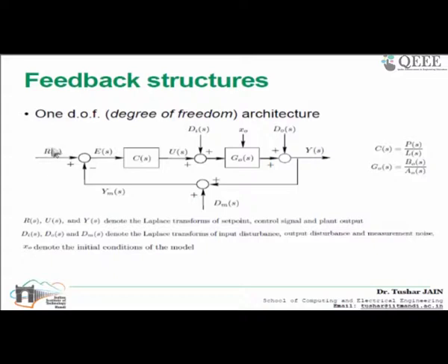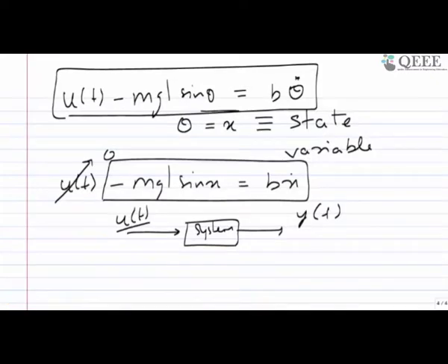This is the external input which a user gives to this closed loop. Why am I calling it a closed loop? We have a G naught, I have a controller which you have designed, then you fed back this output to the input of the controller. So this basically forms a loop which we call a closed loop. If you try to visualize it, we have a system, you give the R(t).